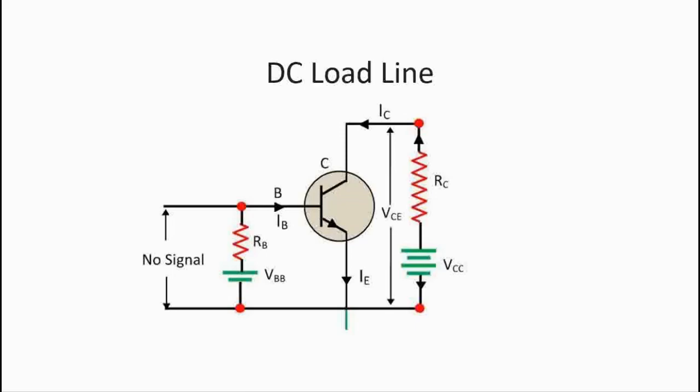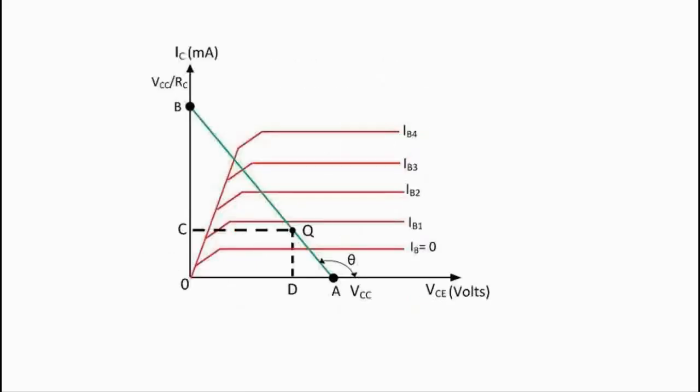and the transistor becomes biased. Now considering a CE NPN transistor circuit as shown here, where no signal is applied to the input side, for this circuit the DC condition will obtain, and the output characteristics of such a circuit are shown in the next figure. Here we could clearly analyze the DC load line curve. The load line analysis can easily be obtained by determining the output characteristics.